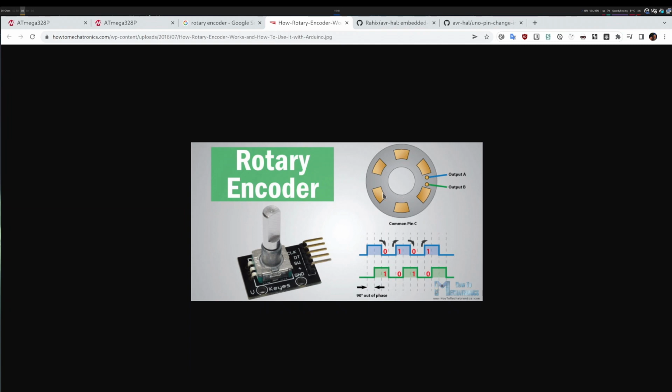Generally, you can keep rotating this encoder, and there are bits connected to either ground or power. So as soon as this part connected to power hits one of the pins, that pin will go high. If I turn towards the right, let's say blue would be, I will call it the clock. If I turn this towards the right, blue will turn high, but green will stay low. And if I keep turning, at some point, green will go high, and then blue will go down. So generally, when I turn towards the right, first the line that I call clock changes, and then only the other line changes a while later. So this means that the values are out of phase.